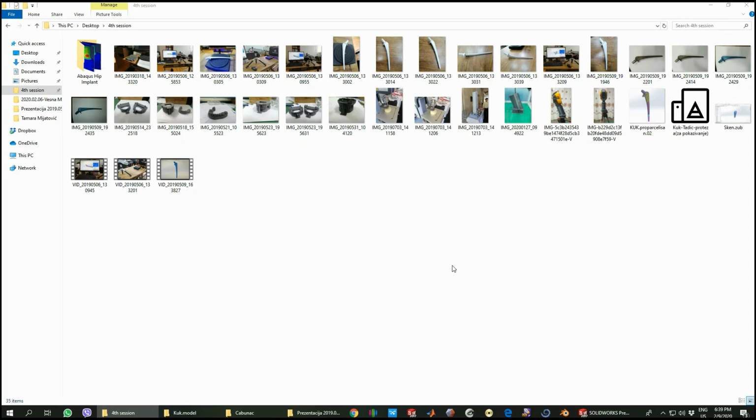First you have to CAD model your model. Then you have to convert it to an STL file. You need to tessellate your CAD model to work in a slicer software. In slicer software you generate printing paths for your 3D printer to perform. Then you upload that file to your 3D printer, you perform your 3D printing, and when the 3D print is finished, you maybe have to, or not, post-process your model to its final look.